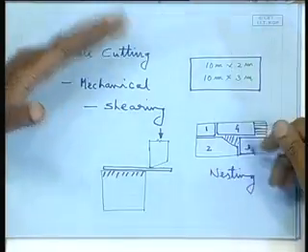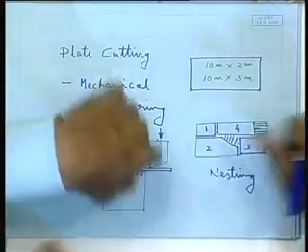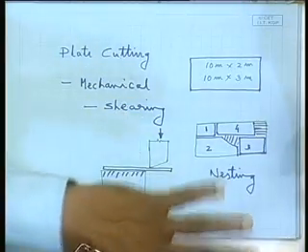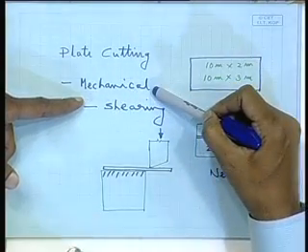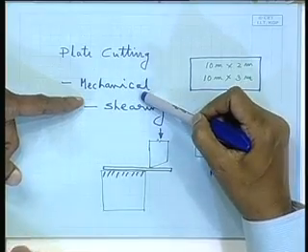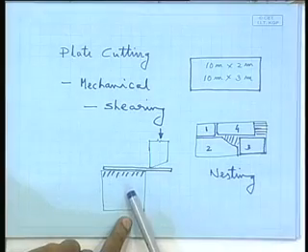Once that is ready, it comes to the cutting bay. That nesting business is a part of a design job essentially, right. Once that information is ready, you take the plate to the cutting bay, the digital information drives the numerically controlled cutting machine and it cuts it. Okay. So, now we come to what the cutting processes are. The first thing I have mentioned here is a mechanical process, and in the mechanical process what we do is essentially shearing. The cutting is done by shearing. Schematically it can be shown in this fashion.